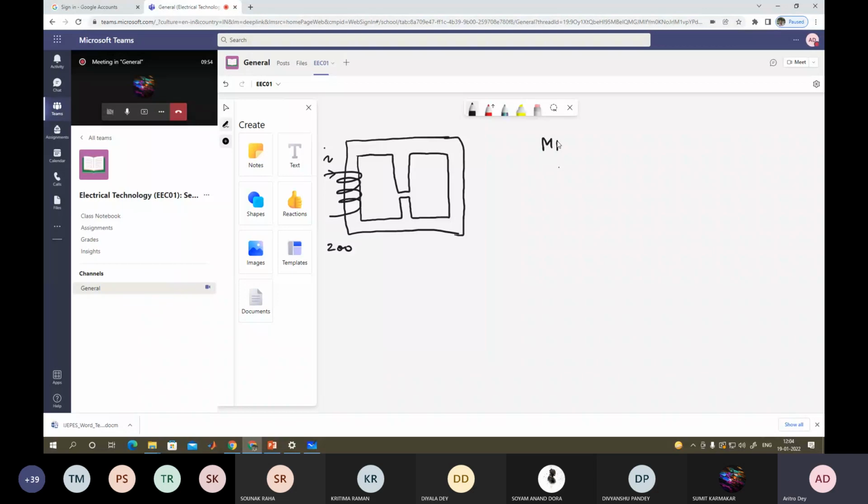That is our mmf. Now through this path, flux lines will originate from here, and it will have two different paths, and it will come and close the circuit like this, just analogous to an electrical circuit. So if we draw the circuit, then it will be like this. This is your mmf. Like the electrical analogy, this path will have certain resistance, which will actually be reluctance. So this is say S1, this is your S2, this is for air gap Sg, and we close it like this.